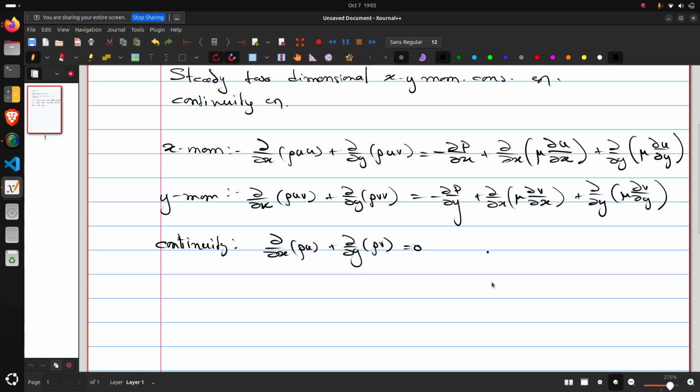So unlike the general scalar transport equation that we were dealing with from the beginning of the course, we can see a difference. The difference is that these equations are highly nonlinear. By that I mean that in this equation, the U's are the unknowns. We are solving for U, which also contains the V velocity, and this V velocity comes from solving the Y momentum equation, right? So to solve one equation, you need to solve the other as well. So this is a highly nonlinear and coupled equation.